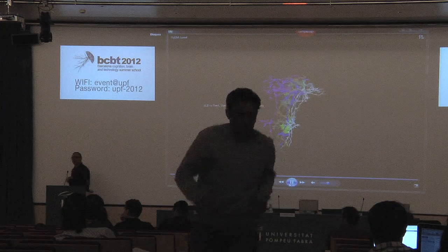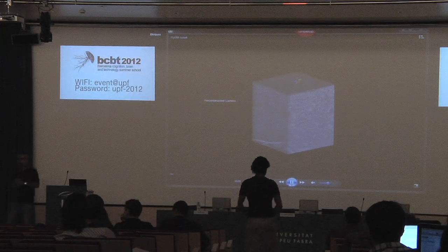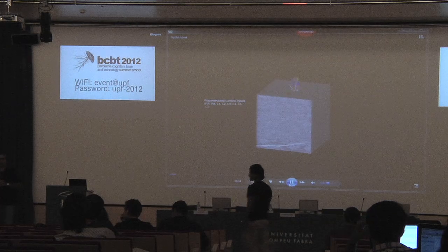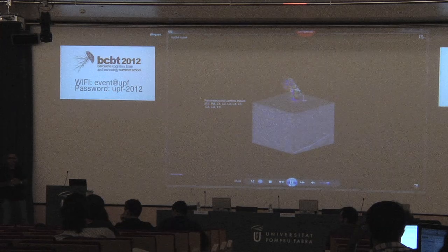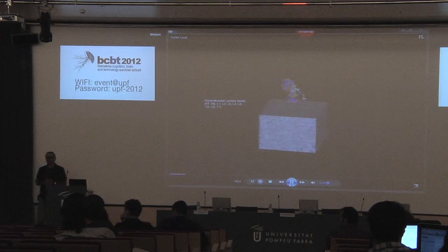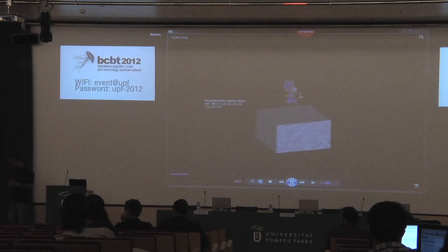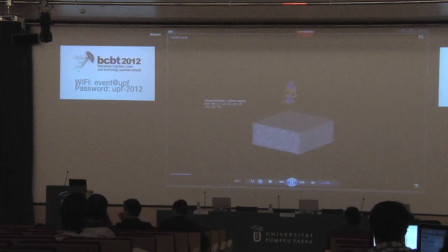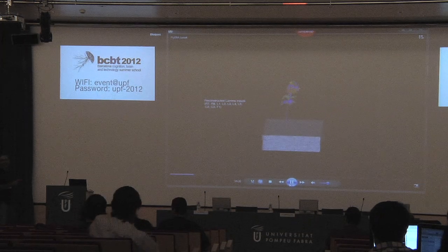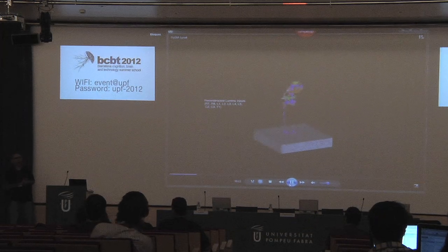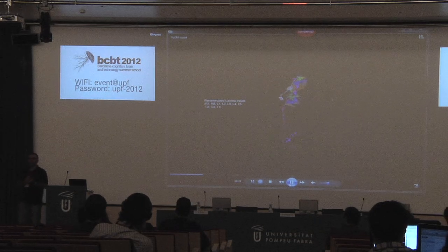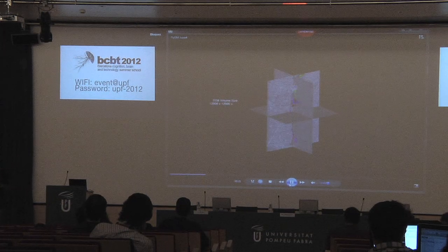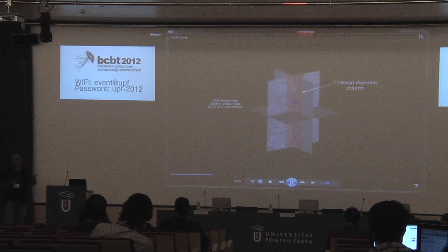So it's really interesting, the lattice filters. I think one of the properties they have is they are relatively insensitive to round-off error when you implement them in finite precision arithmetic. And that's probably related to the dynamic range issue. Exactly. There are many very nice properties. One of them is that they're less sensitive to rounding off errors. Also, they do much better for ill-conditioned problems. So when there are strong correlations in the input, they do better than just finding a single linear filter.